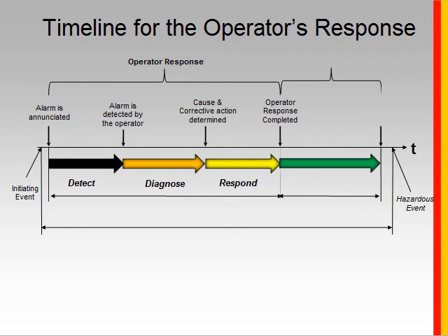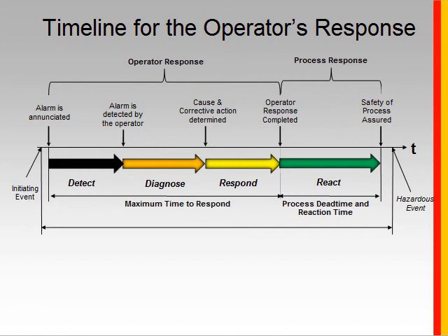Well, once the operator has completed his response, we're not out of the woods yet, because in many cases the process has dead time and doesn't respond immediately to the operator's action. So we need to factor in the idea that the process needs some time to respond to the action of the operator. We'll call this the process response time.